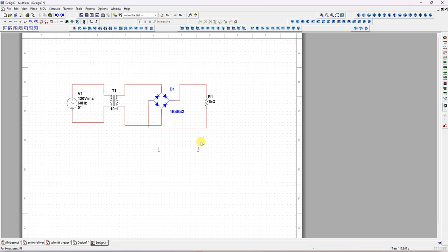Control Z means undo. Now you have to connect this ground here. I cannot start from here. See here, I want to make a connection to this, but I cannot start from here. I told you, you can always start a connection from the edge of the component. From this I cannot start any wire, but here I can start. Okay, so now the connection is over.